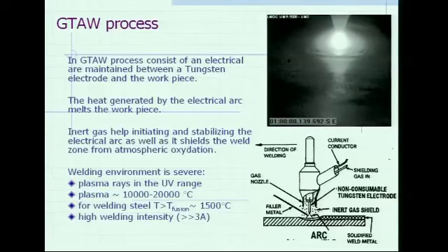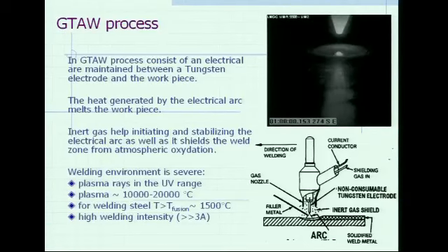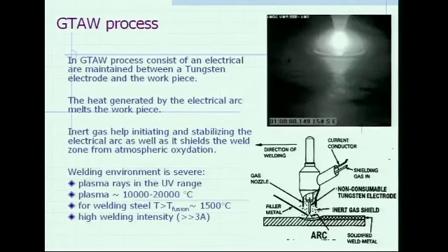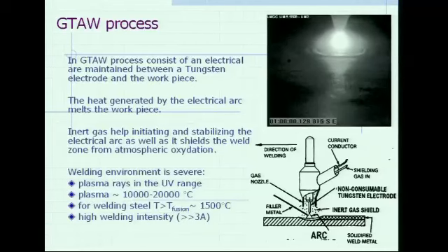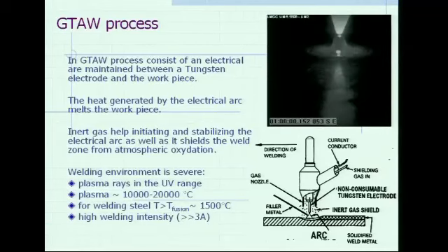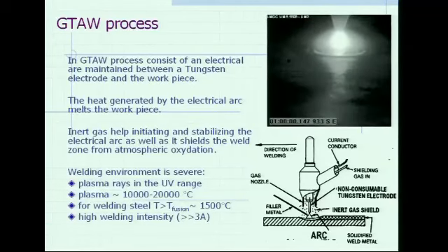So here you can see an electrical arc. It is recorded by a high-speed camera. I don't remember the frequency, it's probably around 8,000 Hertz. And we use a UV filter to cut the electrical arc. I don't know if you have seen a welding process, but it is impossible to see directly, and it is quite dangerous and harmful because we have lots of ultraviolet rays coming from the electrical arc. And you can see quickly the weld pool moving due to the arc pressure.